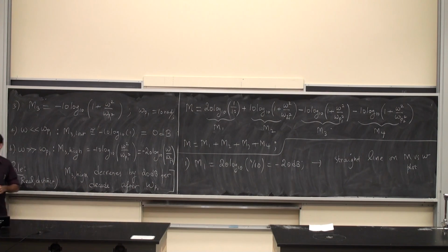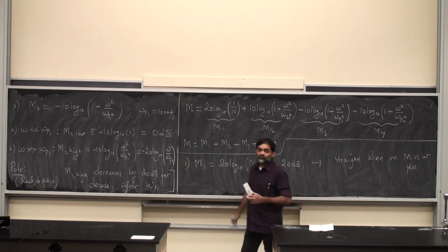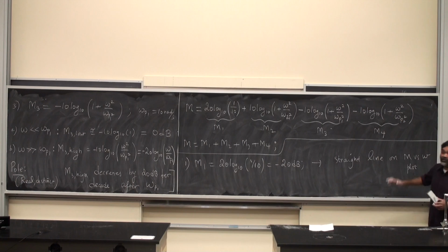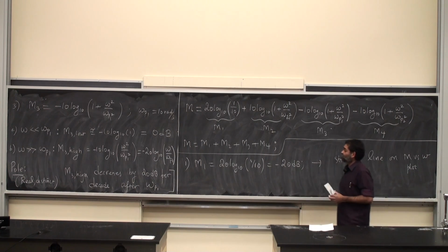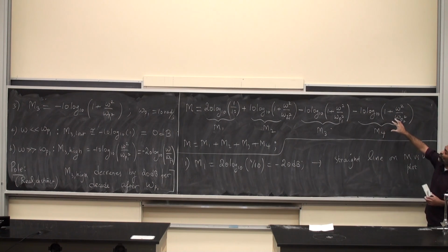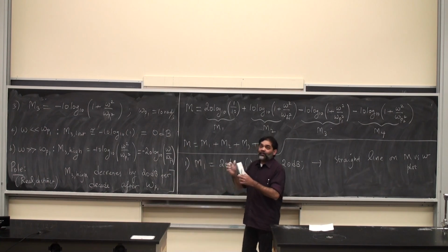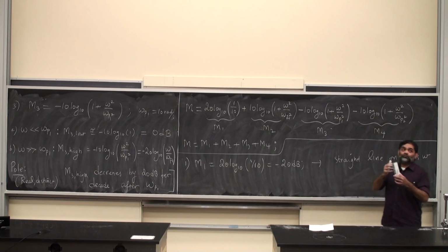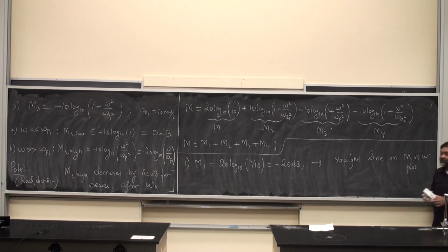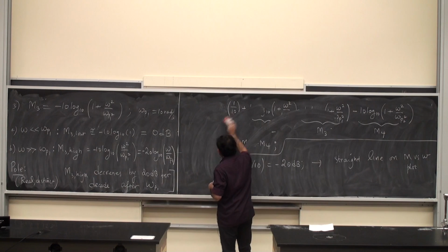Last chance for questions. Is this clear to everybody? It could be boring, mundane, and all these things, but I still have to do it. I'm going to do it step by step. Okay? You've got to do the same thing for M4. I'm going to wave my hands on that because this is another pole. It's a real distinct pole. Its behavior is exactly the same as this. Right after I go from omega P2, which is 100 radians per second, I decrease by 20 decibels. Okay? So I'm going to summarize this behavior by writing everything down.